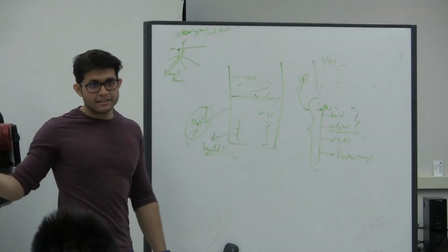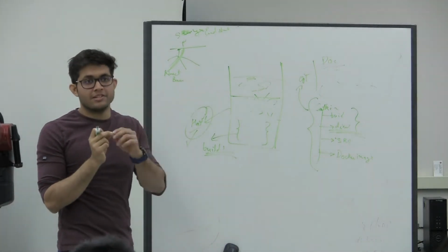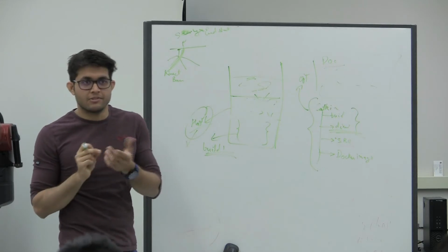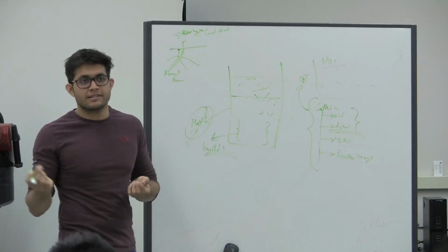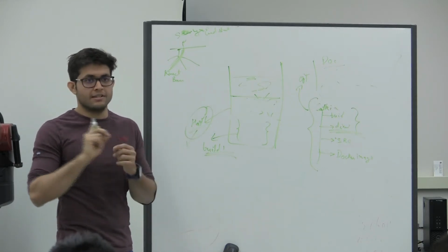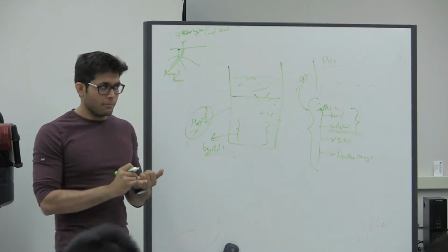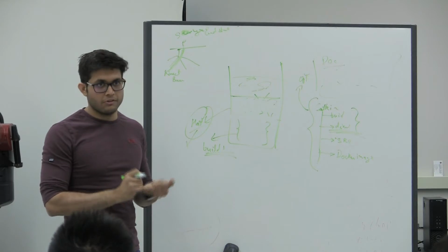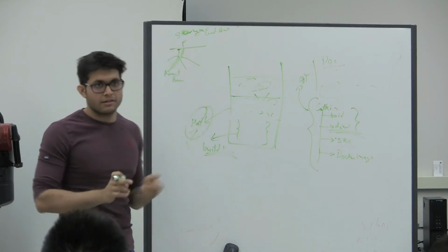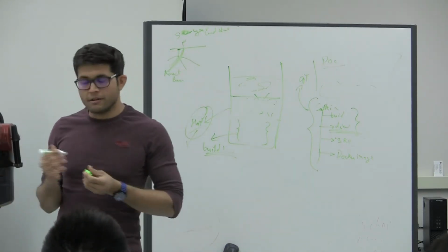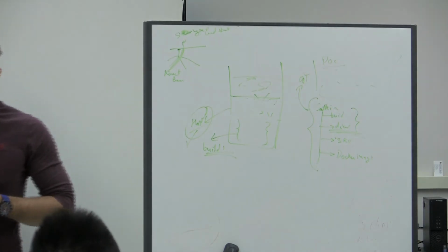This link doesn't have dimensions, it's XYZ 000, and the type of link is fixed, instead of rotational or translational. You give it a fixed link, position and orientation 000, which means it's directly connected to this part. So now it configures everything by itself and it knows the position.